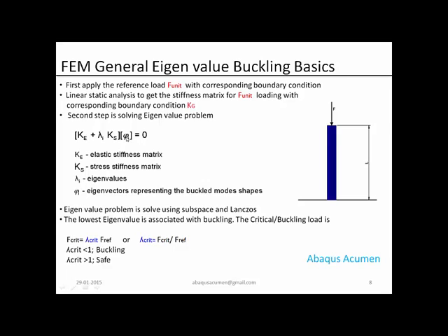Whatever eigenvectors you get, whatever displacement you get out of this equation, they are not a real displacement, but just a representation of the buckling shape. So this is a brief overview of the fundamentals of the finite element eigenvalue buckling problem.